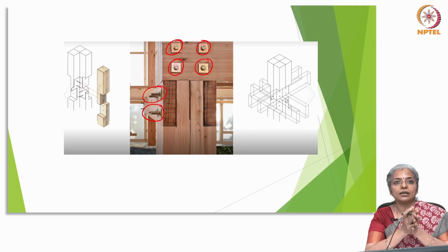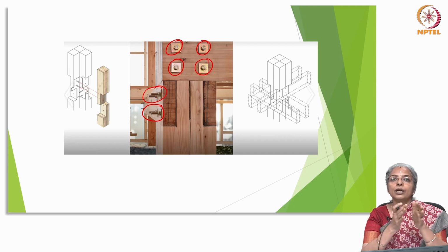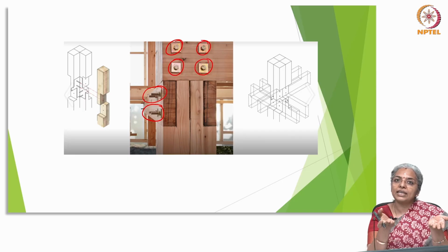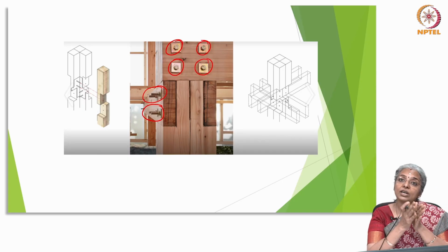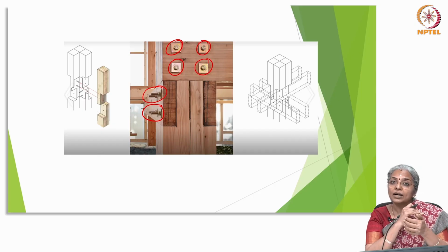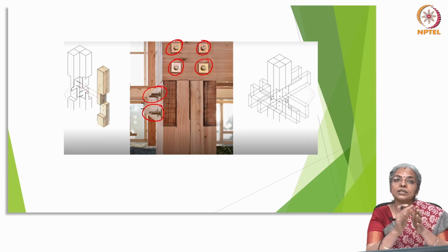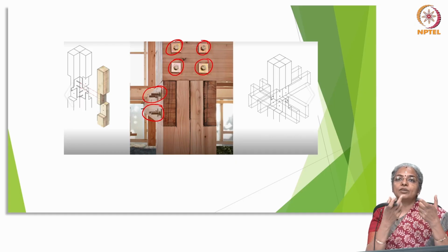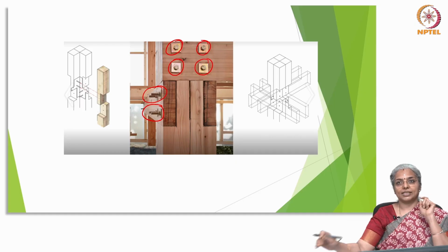Now, if instead of these nuts and bolts they would have used adhesive, you wouldn't know at what point the adhesive is there, how to detach the adhesive, what is the nature of the adhesive, do you have a solvent for that adhesive, or you will have to end up cutting off that particular piece. You would know nothing of this. So, it is best to use joints which are visible and which we can detach easily.